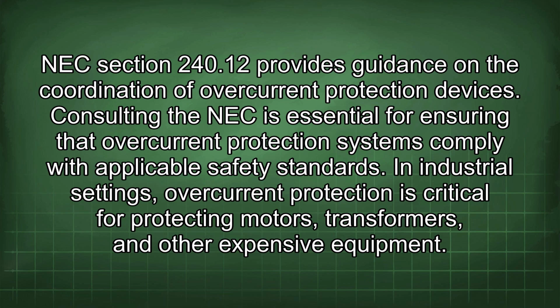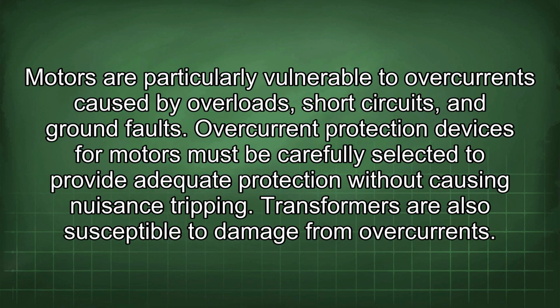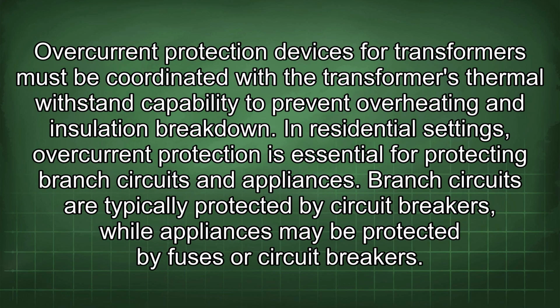In industrial settings, overcurrent protection is critical for protecting motors, transformers, and other expensive equipment. Motors are particularly vulnerable to overcurrents caused by overloads, short circuits, and ground faults. Overcurrent protection devices for motors must be carefully selected to provide adequate protection without causing nuisance tripping. Transformers are also susceptible to damage from overcurrents. Overcurrent protection devices for transformers must be coordinated with the transformer's thermal withstand capability to prevent overheating and insulation breakdown.